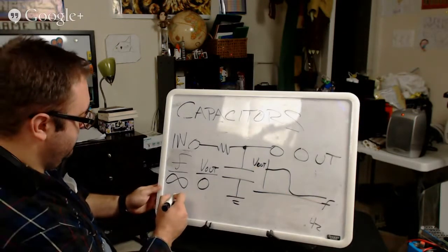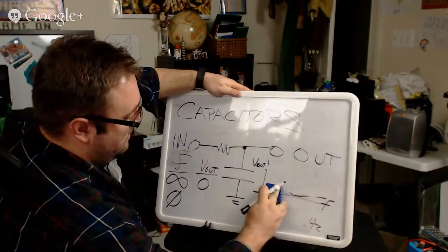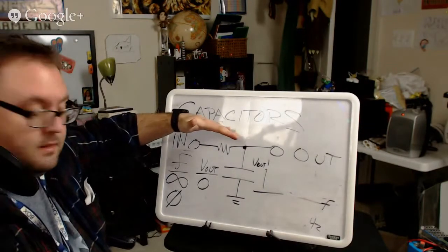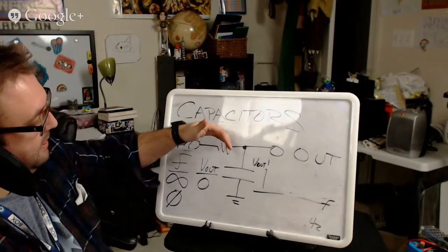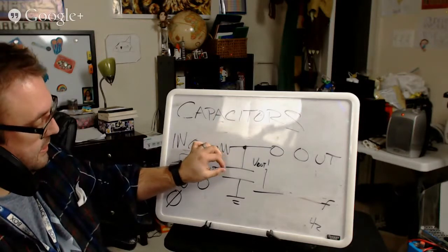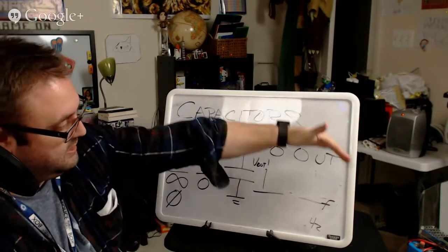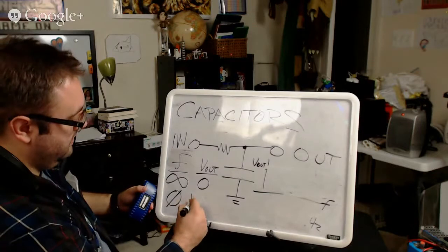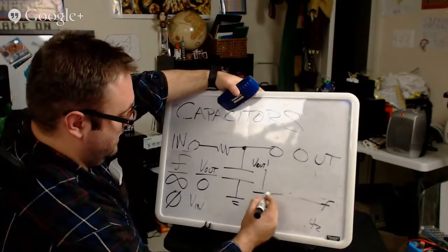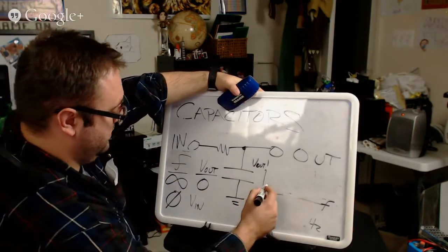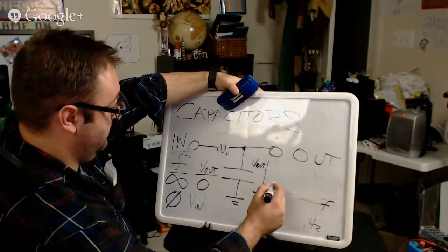If, on the other hand, my frequency approaches 0, there are leakage currents and whatnot, but for the most part the capacitor now becomes an open, really high resistance, so my signal goes straight to the output. My V out tends to equal about my V in. Or another way to look at it is at these really low frequencies, I'm having a high, or did I draw that backwards?